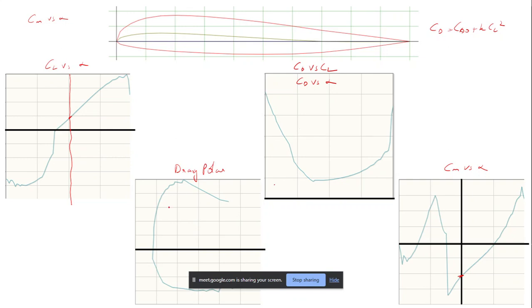So this is the typical profile of a drag polar. Okay, so you have this region here. It's called the laminar flow region, laminar bucket. I'm not sure what the term was. Similarly, here you have the drag bucket, this area. So try looking at these typical things in the graph. So you have CM naught negative for a cambered airfoil. That is how we identified this one.